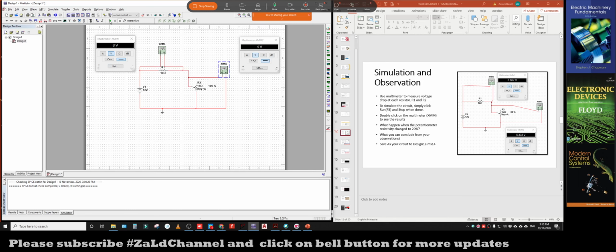So if I click on simulation again, you will see the voltage divider is now divided into half. 6 volt across here, another 6 volt across here, because this resistor is now 100%, which is 1 kilo. So you can just play around at home, by dragging this value of the resistance, for example 20%. What about 20% of R2? 20% means 200 ohms, right? So meaning that you have changed the resistivity of this R2 to 200 ohms.